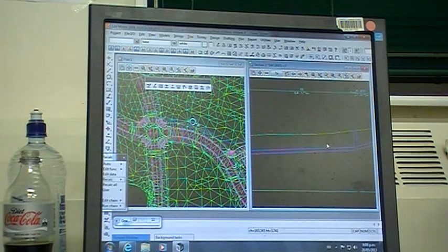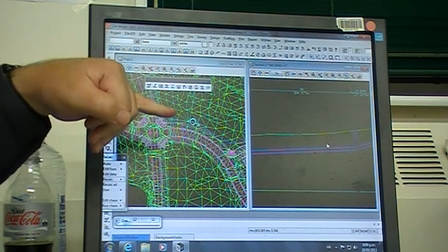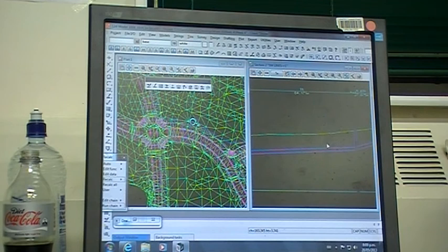The more that a drain layer has to dig down, the more he has to bench out for safety. Do you understand what I mean by benching out? Yep. Okay, so there's a cost involved. The minimum depth: you have to have a 1.2 cover over the top of the pipe underneath the road. It's a lot less once it gets into private lots, but it's still got to be practical. So if you're working at that 1 to 1.2, that's good. When you get beyond 1.8, then you're starting to get into additional cost.